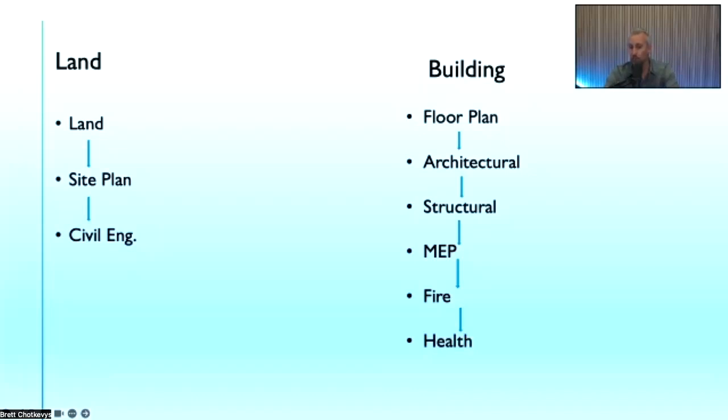Then I had to take those drawings and send them to a structural engineer. So a structural engineer will take those and build out, he's going to call for all the different beams and headers and pieces of wood, right? You're going to need, these are going to be 2x4s. These are going to be 2x6s. These are going to be like LVLs. Here's going to be your header. Your support beam is going to be here and here and here, right? And they have to run all of these calculations on these things.